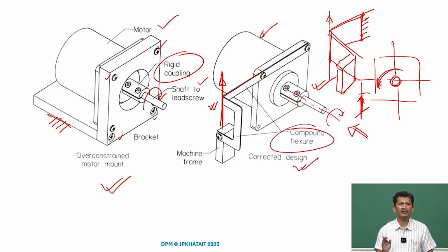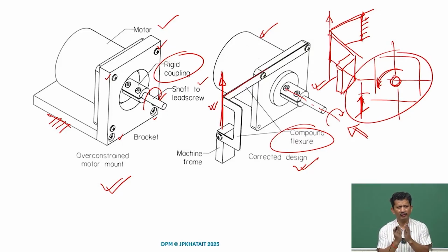So, not necessarily do we have to use many parts or a lot of tooling or make precise adjustments with a lot of jigs and fixtures. Sometimes if you understand the requirement, in this case, a simple flexure of a folded sheet with a sharp bend will do the job.